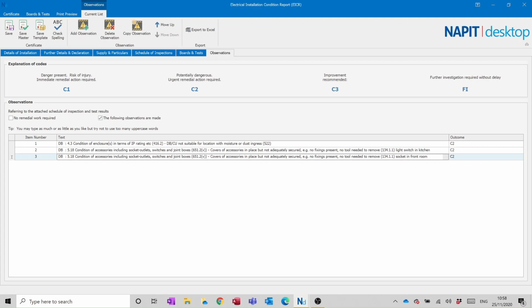That comes down to, again, handing this to a client who needs to understand it. If you've got pages and pages and pages of codes for a domestic property, there's every likelihood they're not going to read them. So it's often better to make the generic statement on the report of why you've come to the conclusions you have, and then actually go around with the client and show them. That's often the best way. But certainly when you're producing commercial reports, you need everything listed and itemised. It's always a good thing to do that, because you're often not given the opportunity to walk around with somebody and show them a huge installation in full and everything you've identified. It's going to be passed down to other electricians or maintenance people to look at. So there's that one there.